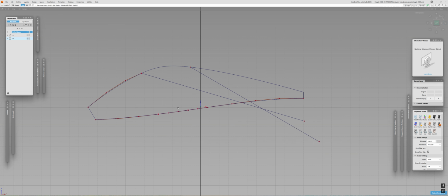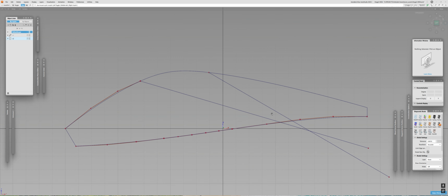Yeah, it will be really difficult for me to use these parts, especially here, but everywhere, because the angles are too extreme. So ideally, what you want is to have natural and really good angles which are relatively within 90 degrees plus minus like 30, something like that. And then you will be just fine. It will be easy for Alias to align.